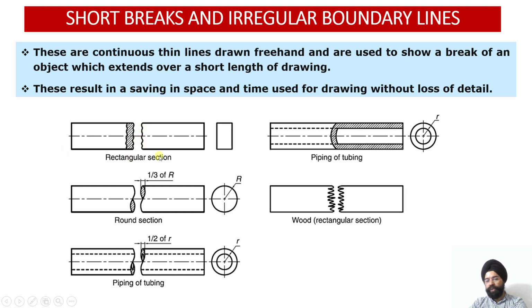So I am not going to draw this to the scale, but this dimension I will be drawing to 1:10 or 1:2 or 1:5. So this reduction in scale I will do only on this side, whereas this length I can manipulate as per my requirement, and this break line will indicate that whatever length I am showing over here is not reduced to 1:2.